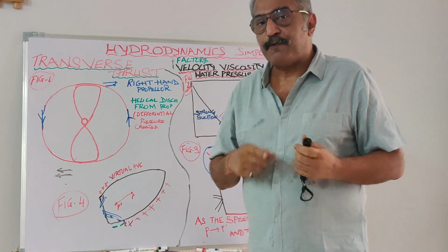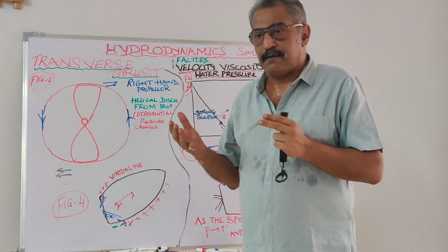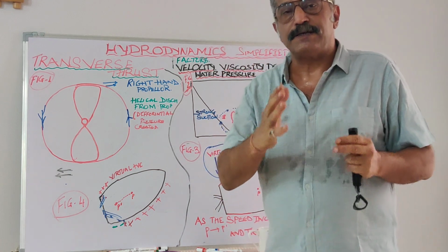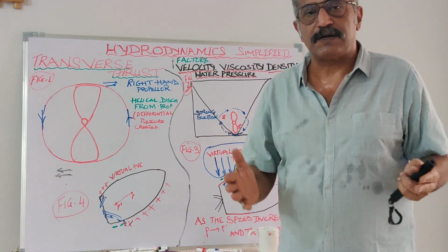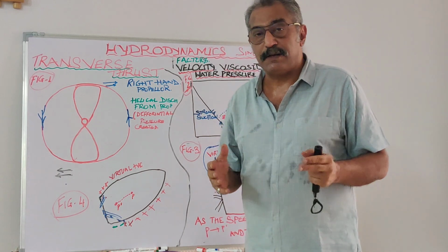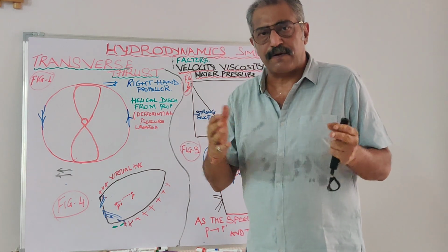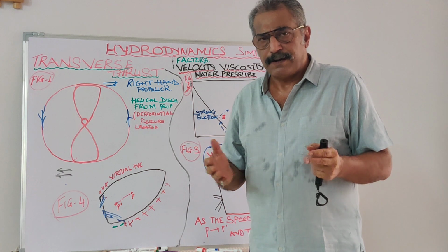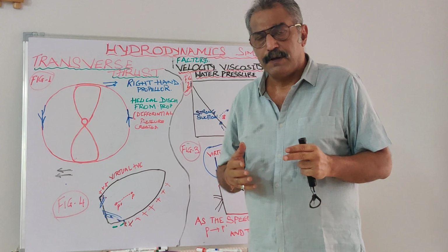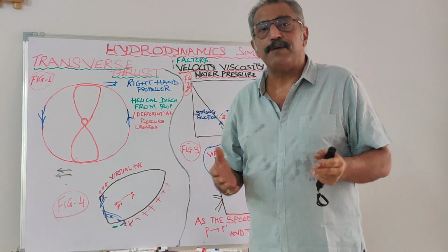At that point of time, you must have realized that in a narrow channel fairway, when stern thrust is required, or when it is required to cant the bow in a shorter time, normally the pilots ask for a tug. It is something similar when we are going alongside. We have the property of transverse thrust, but it's normally not very pronounced because I'm talking about shallow waters. In deeper water, the water pressures are high, and the effect of transverse thrust is very much pronounced.